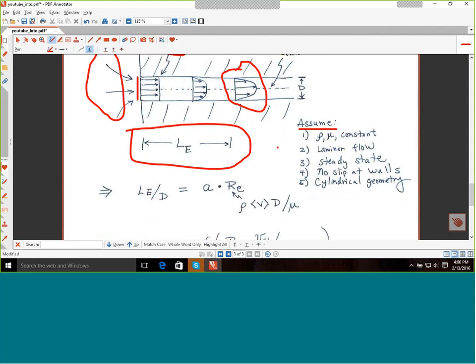Well, the actual answer to that is because you approach parabolic flow asymptotically, it would actually take an infinite length of tube to get to truly perfectly parabolic flow. So any description of the entrance length incorporates within it some parameter for a tolerance for fully developed flow. And often it's the percentage approach of the centerline velocity to the centerline velocity for fully developed flow.